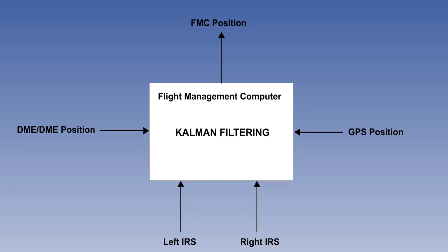This lesson is the last of 3 on the Inertial Reference System, or IRS. Previously, we said that there were 3 main characteristics which define what we now call an IRS, which make it recognisably different from a first-generation standalone INS. These were greater system integration, the use of ring laser gyros, and much greater computer power.